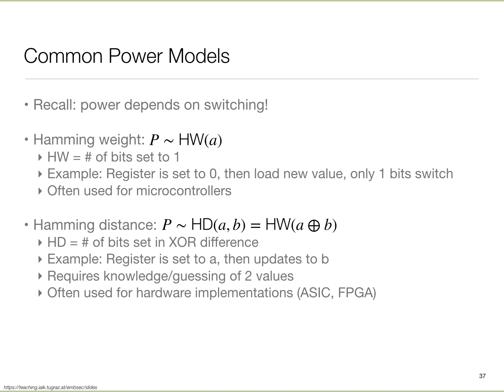Another method in the same vein: all these things that I talked about, instructions and all, had an under-the-hood assumption that there was a clock tick and precise instruction boundaries. What if I were to have a clock whose edge I move around a little bit from clock tick to clock tick? Instead of a perfect, let's say, 100 megahertz clock, my clock edge is a little bit earlier or a little bit later, and I spread it around.